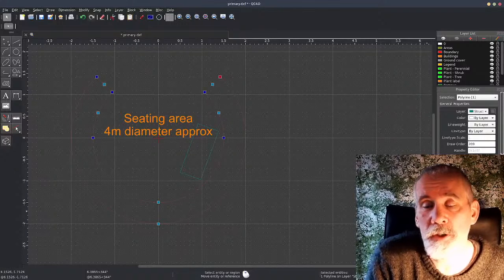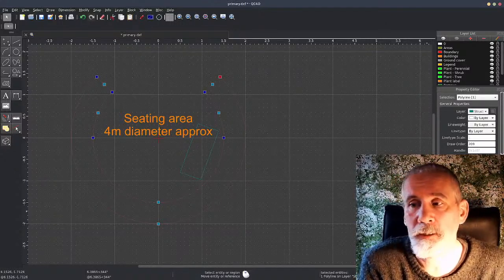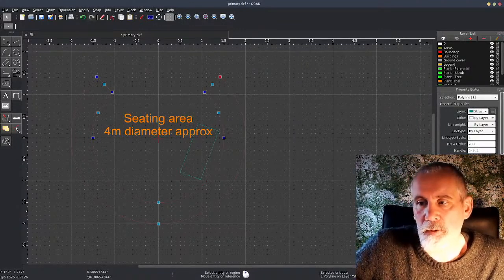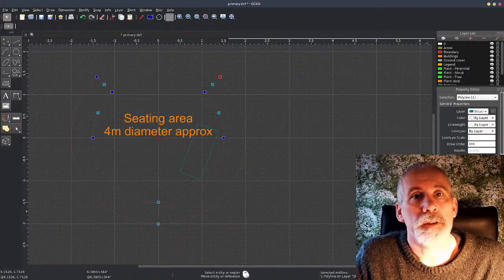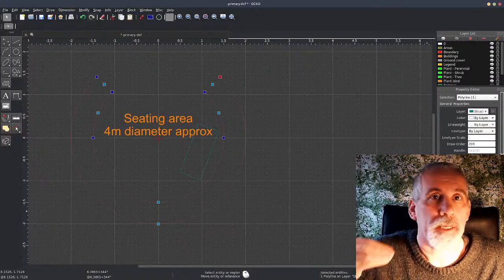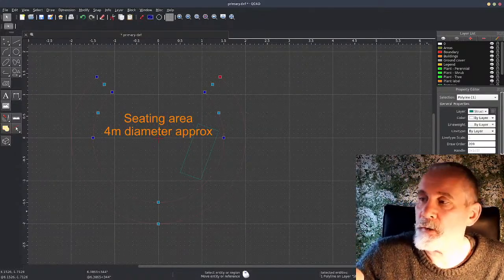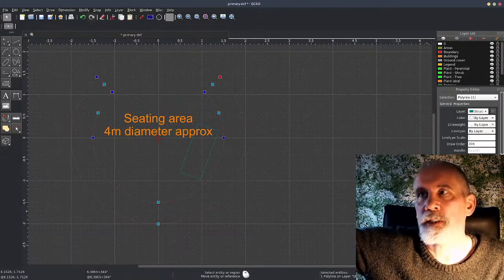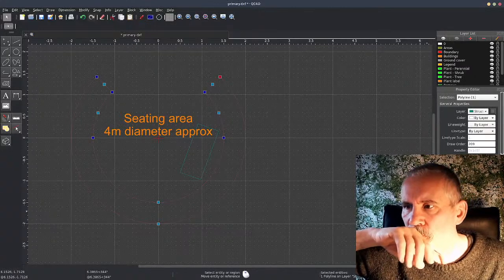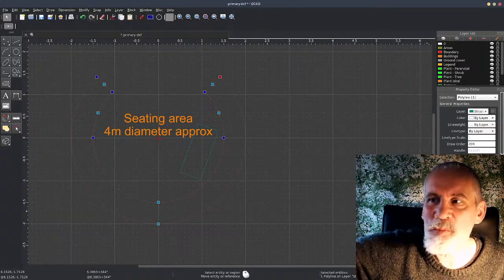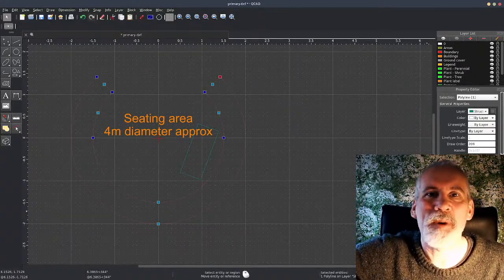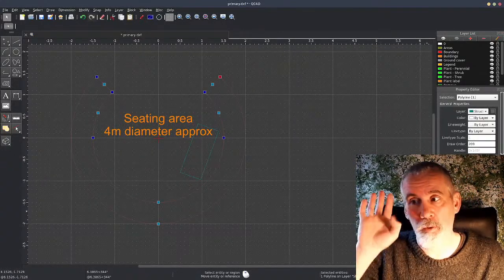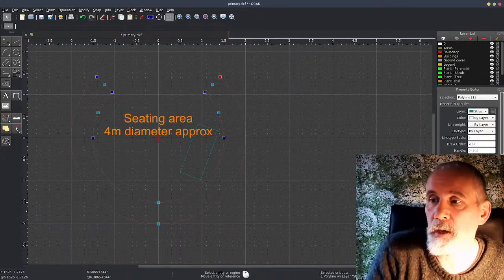This is useful for planting ground cover, or for working out your planting density, but it's also super useful if you're doing any kind of hard landscaping. You can work out how much material. So I know there's 4 square meters, and I can work out the volume. It's going to be roughly 40 centimeters high, I think. So you can work out how much rubble you need to fill that gabion wall. Yeah, that's worth its weight in gold, that is.